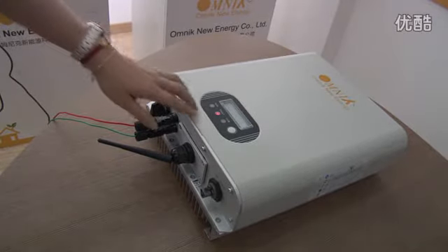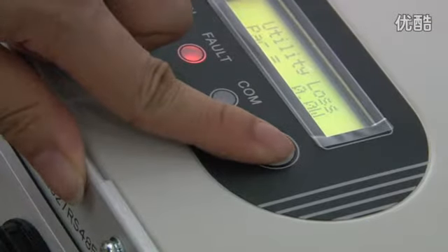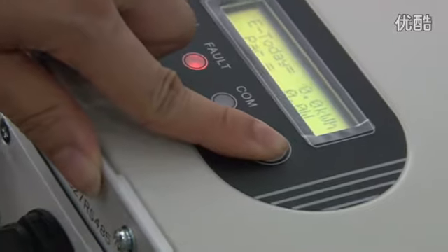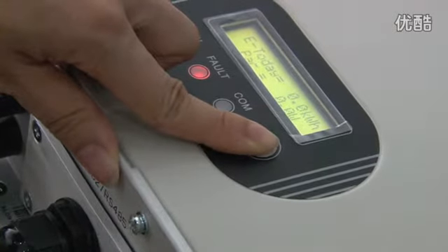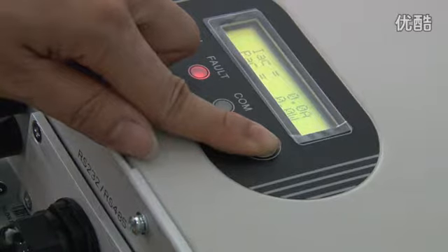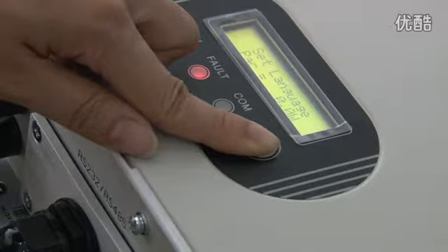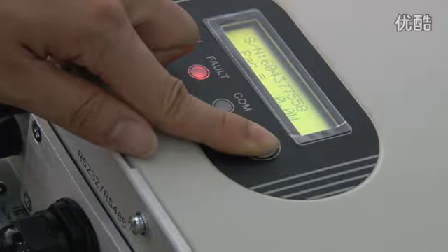The screen will show you quite a lot of parameters. First is the inverter working status, the total generation today, and the total generation from installation, the input voltage, input current, output current, grid frequency, inverter type, inverter software version number, language setting, grid voltage, the Wi-Fi card serial number, and IP address.